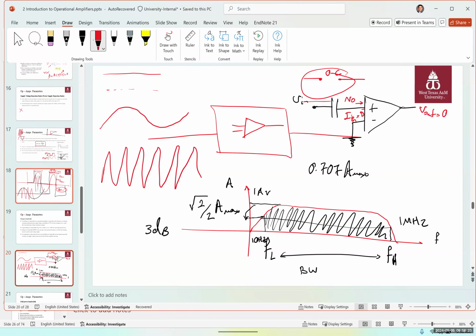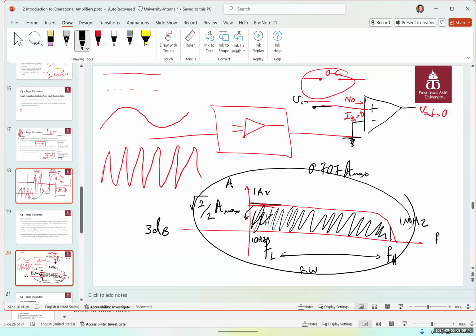These capacitors determine the lower cutoff frequency. Okay. If I didn't have that capacitor, the cutoff frequency could go down to even 0 hertz. So I would have no lower cutoff frequency because even a DC signal would pass through and I would have an output signal. Okay. And then I would create what is called a low pass filter, or LPF.